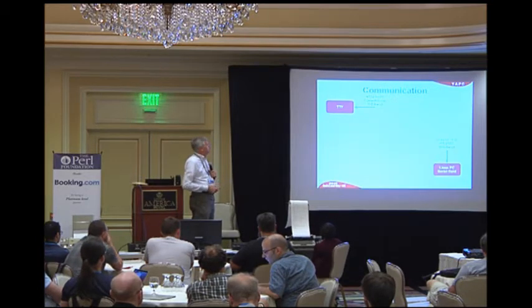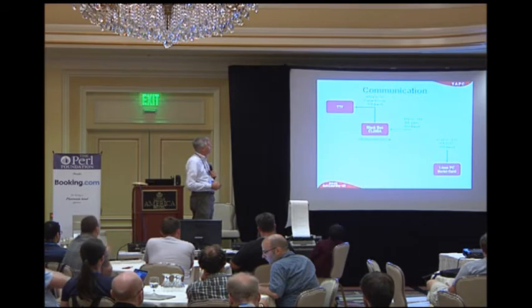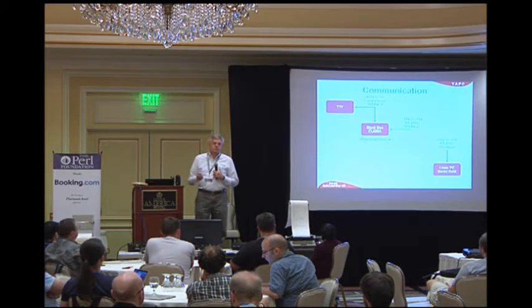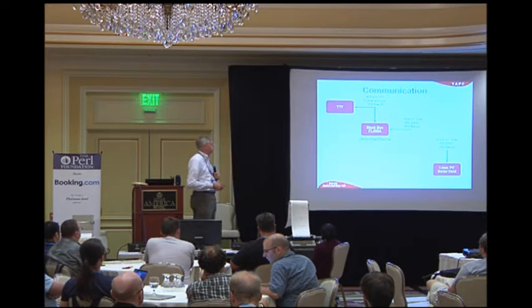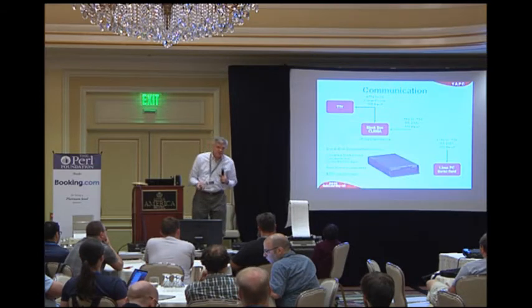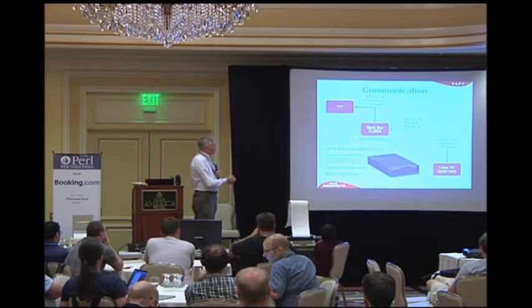So my first step was to get to RS-232. And I just took a passive device that takes current loop and turns it into RS-232. That was an off-the-shelf black box device, and it costs about $270. You can still buy them today. You can get them for 50 to 70 bucks on eBay. But now we're at an RS-232 voltage signal, but we're at different baud rates.